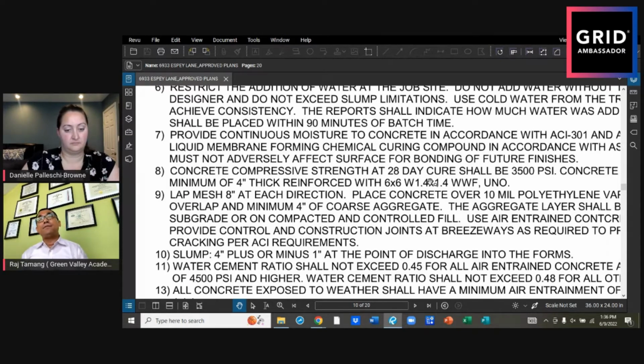And also you have to remember, okay, so you say, Raj, how do I wait 28 days? That's too long. Yeah, like I said, you don't have to really wait 28 days, but it depends. If you do commercial projects, you have to. For a residential project, building a new house, I have not seen people do it. Let's say the starting point is a foundation. Once you do the foundation, you do the concrete wall. After the concrete wall, around 2 or 3 days, people start actually doing the framing.